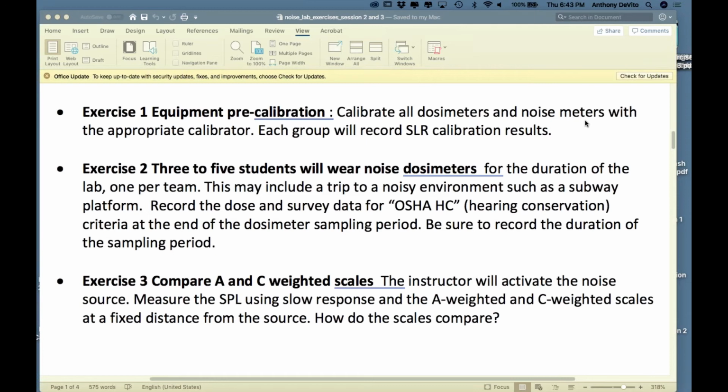So, you know, you can hear it. You could hear it from out there. It's really loud. So you need the right size collar. Notice he pulled the windsock, your wind collar, off of it. That's there because, remember, we're measuring sound pressure levels, and we're talking about very little pressure differences.